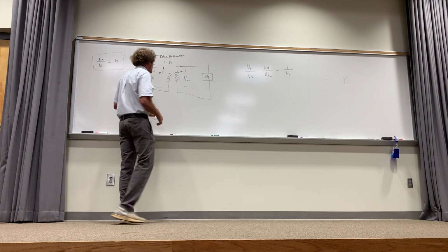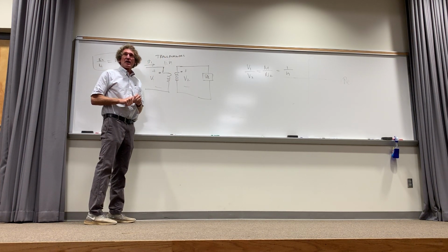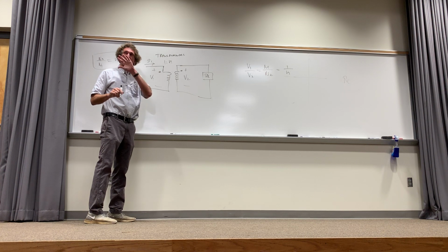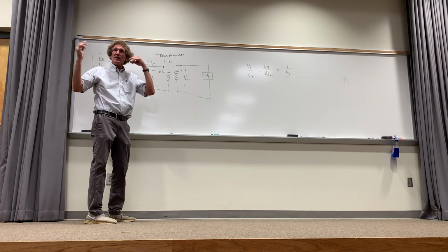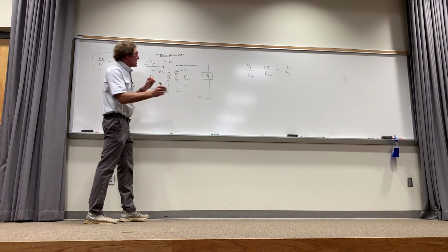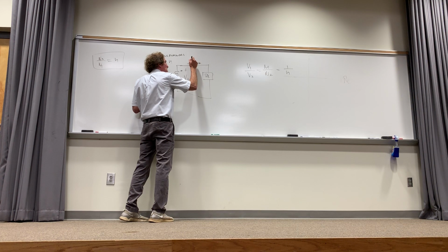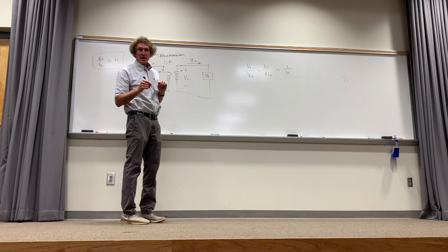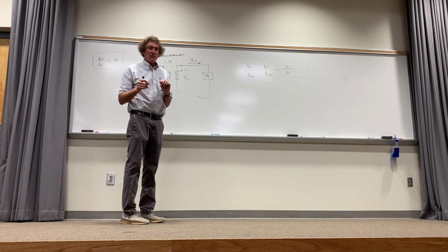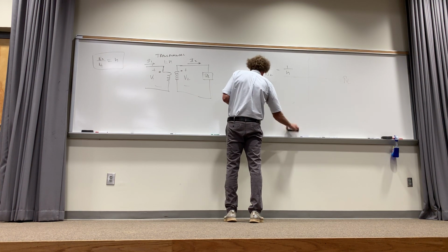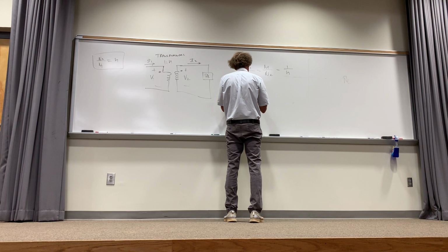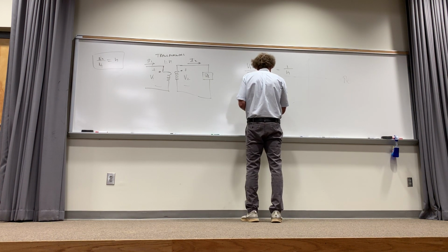Now, that's true. That's absolute. The next thing they do is this. Now this is Dave Irwin saying he does it this way. I'm not sure if everybody does this. This is for transformers, not for mutually coupled circuits where we had the M and the jωL and the jM. But here, they're going to label this current out of the secondary in this direction as I2. Right. Now for that, they also say I2 over I1, or really, let me do it this way to be consistent, I1 over I2 will be equal to simply N.